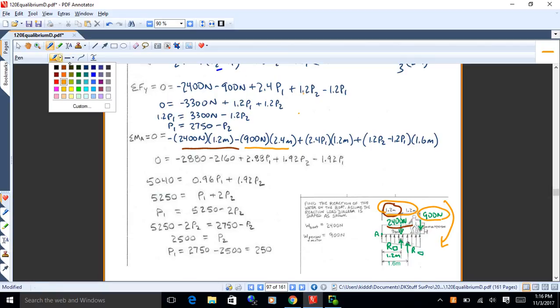Of course, you always have to reference these to the given point that you're working with. And then we've got the reactions. And those are placed at the centroid of the distributed load. So even though the values on the ends of that distributed load are unknown, you do know the locations of the centroid because it's just a rectangle and a triangle. So we've got the rectangular load. That's that one.